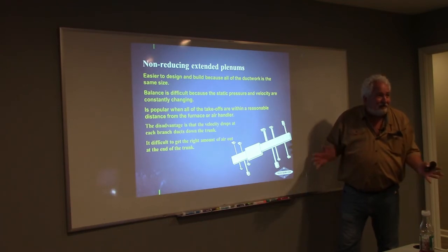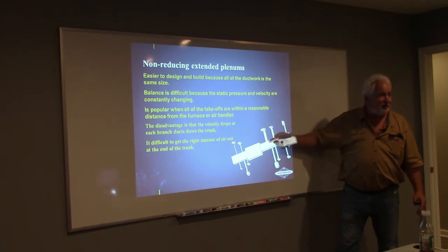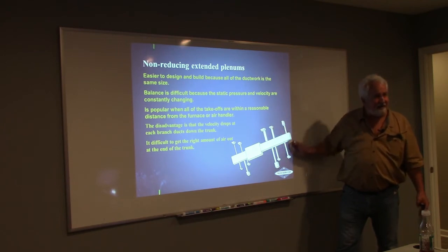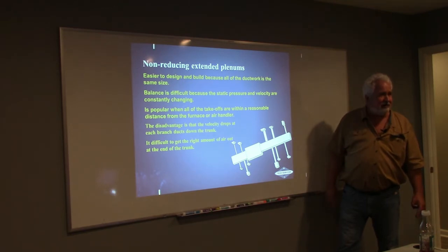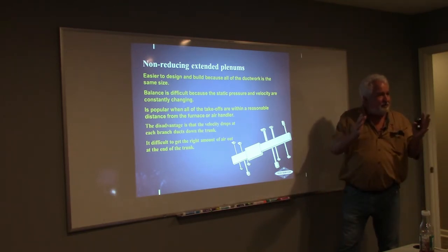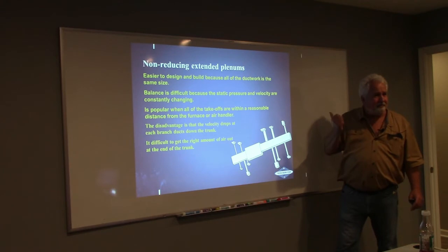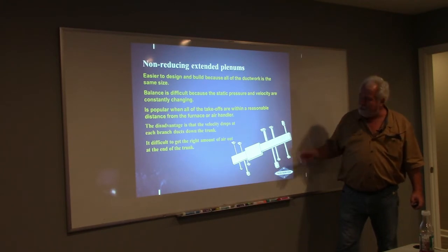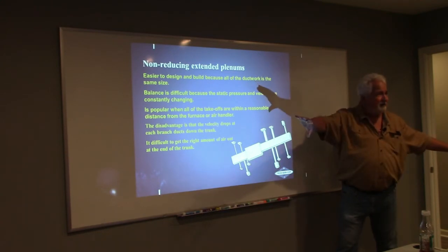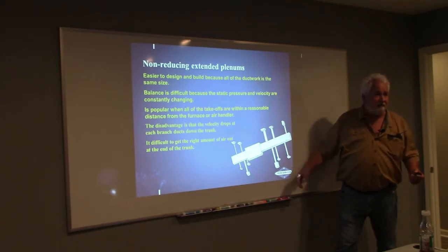I have no pressure in there. I have no static pressure because it all went out here. No static on the side. If I don't have any static on the side, can I convert anything to velocity? The balloon needs to be blown up to be able to have the air coming out. You follow? Cool. So not a great way. It's cheap because it's one size. Don't have to think about anything, but it's lousy for airflow.